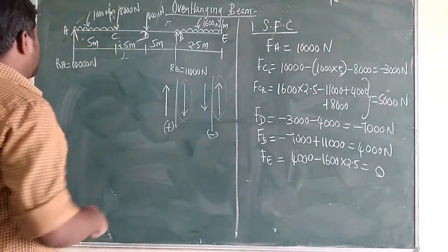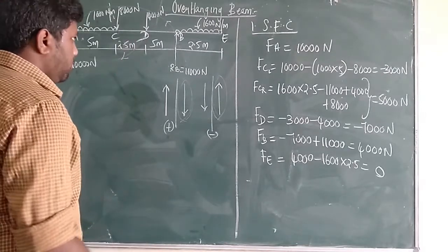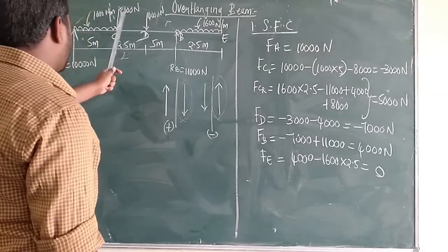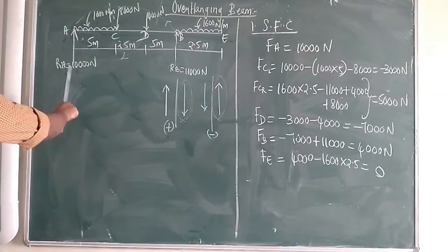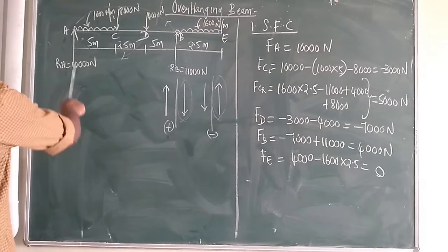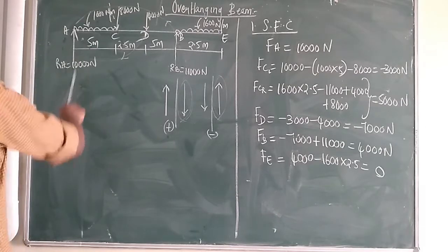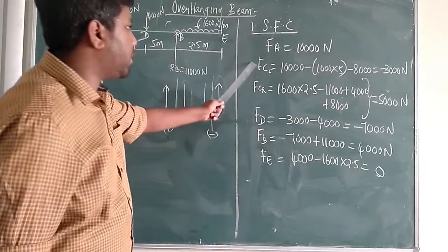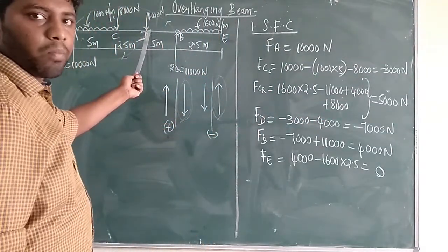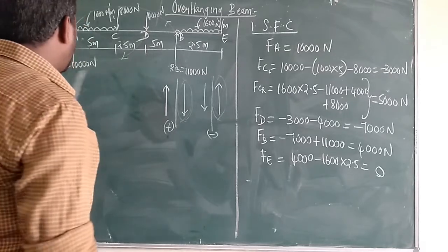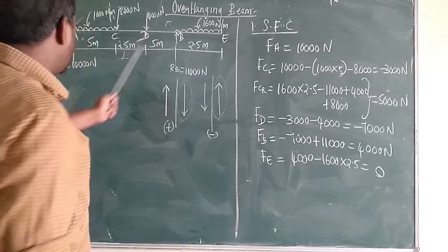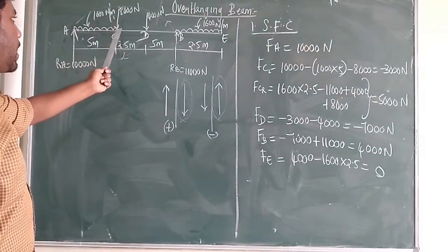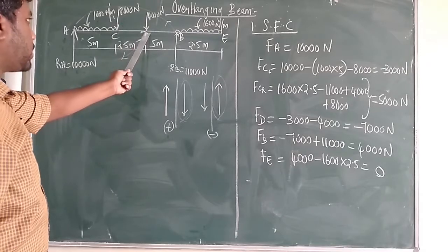Then shear force at D. I am coming from the left of the section. So this is the left of the section, plus 10,000. You already know this thing, only this additional point D is there. See how you will calculate at D at the left of the section. You consider this upward load, this UDL, this downward direction, and this direction.